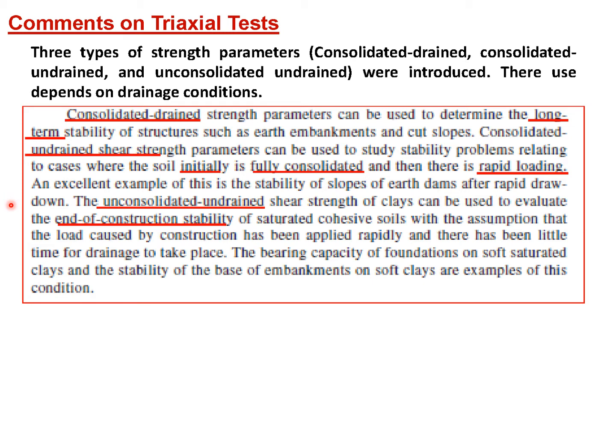The unconsolidated undrained shear strength of clays can be used to evaluate the end of construction stability of saturated cohesive soils with the assumption that the load caused by construction has been applied rapidly and there has been little time for drainage to take place. The bearing capacity of foundations on soft saturated clays and the stability of the base of embankments on soft clays are examples of this condition.